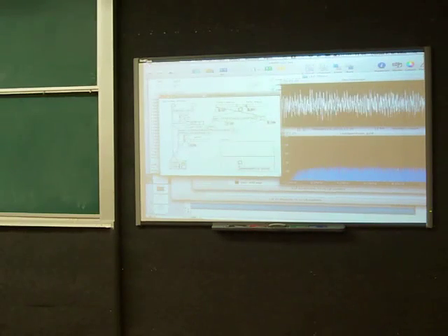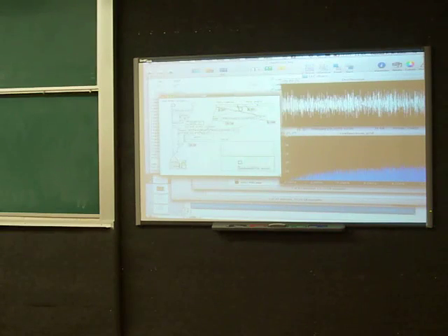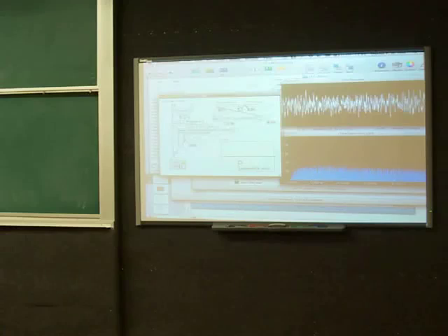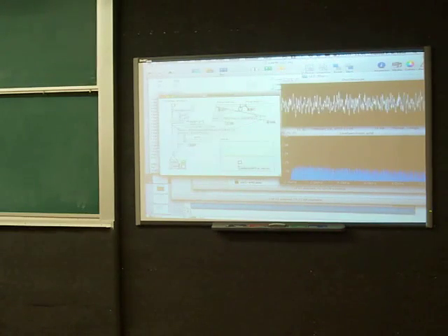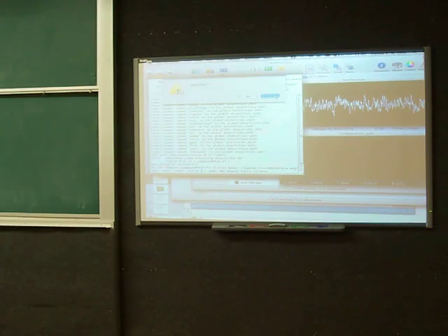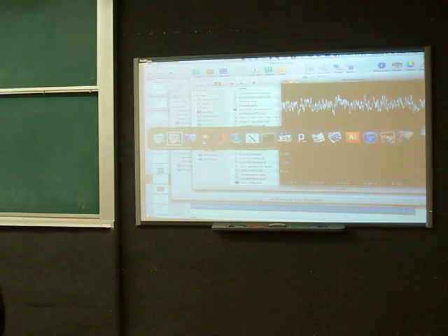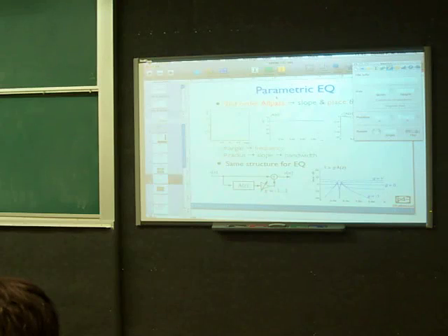So you can hear that becoming a high frequency bandpass signal. Because the sampling rate is so high, I have to make the pole angle very small to get interesting frequencies. There we go. That's it. I blew it again. All right. You get the idea that I can parametrically vary that bandpass filter both in frequency and bandwidth, and then also in whether it's a bandpass or a notch.